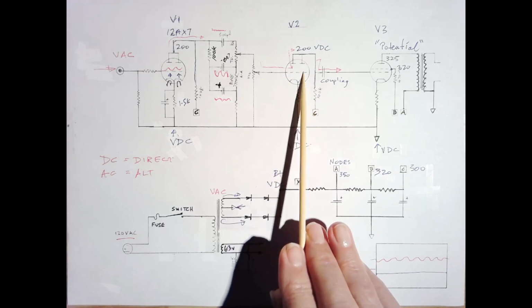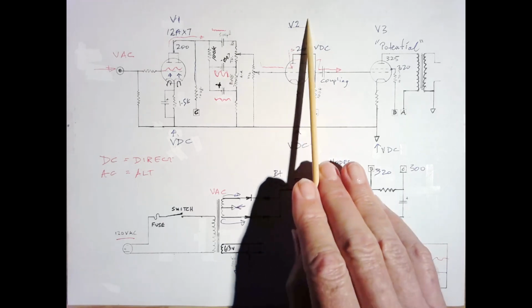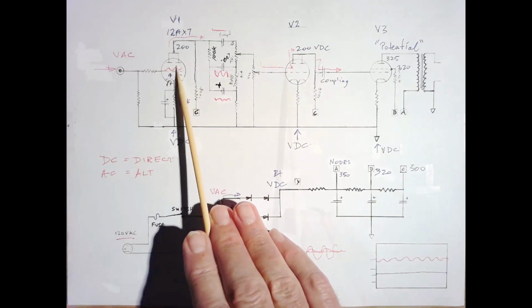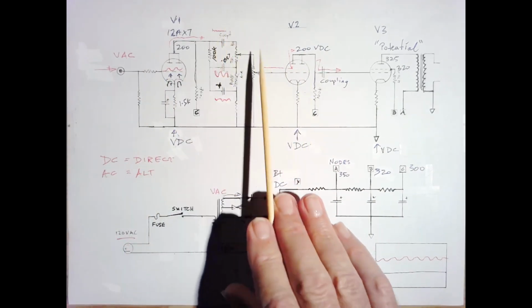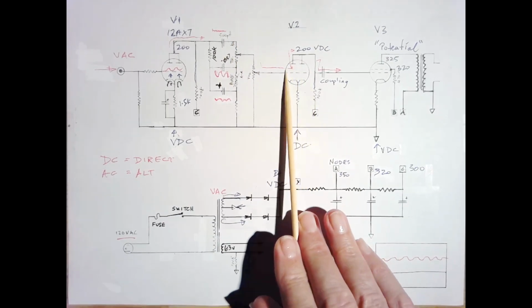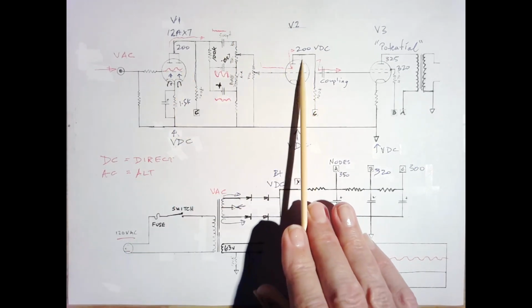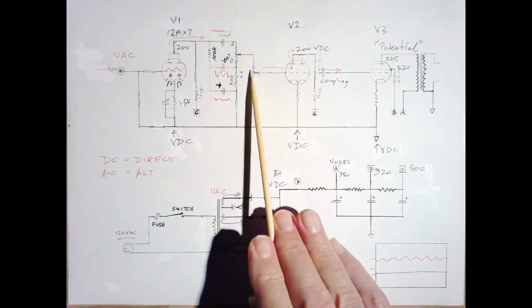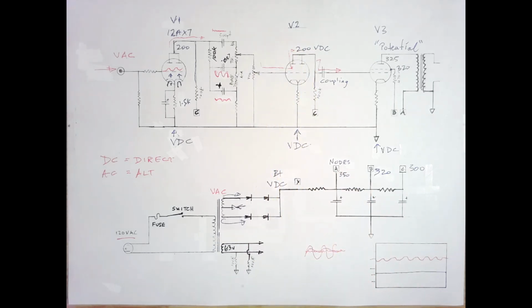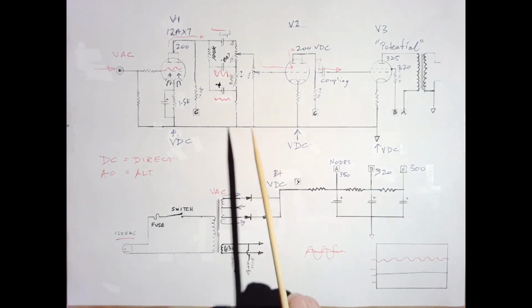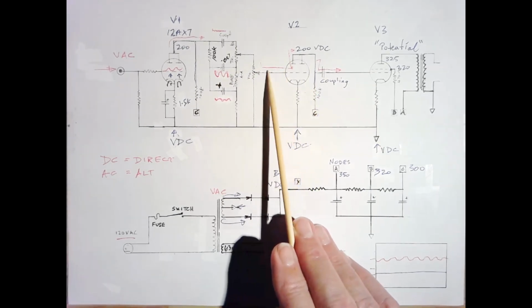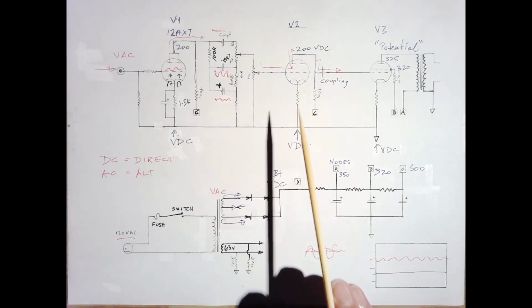It's sending in a big wave, and this is magnifying it enormously, so we get a big signal wave that's been amplified back here, and then by the time it gets through this, it'll be reduced, but it'll still be big compared to what was here, and so that means that we're going to get breakup. It's going to exceed the specs on here. Whereas, and you know, we design amps so that they will have a certain amount of breakup. We like it. It's a nice, pleasing tone. Whereas when you turn it down, you lose the breakup, and it's a much more controlled signal coming in here.